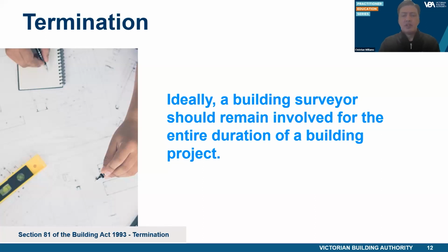It's important to note that only the appointment of a private building surveyor can be terminated. You cannot terminate the appointment of a municipal building surveyor. Where an application for a building permit has been made to a council, the owner is locked in with council for the duration of the project.